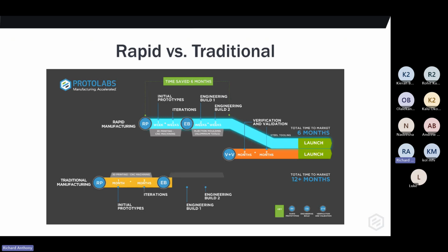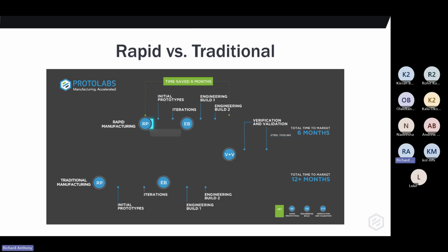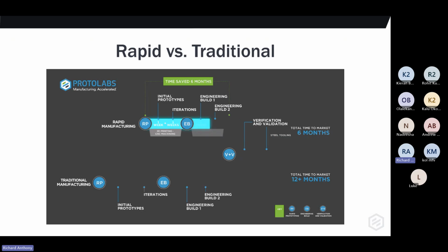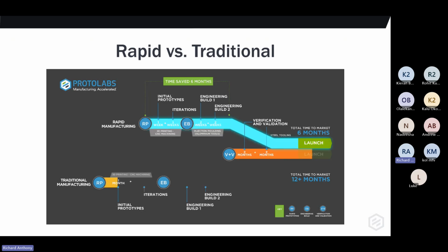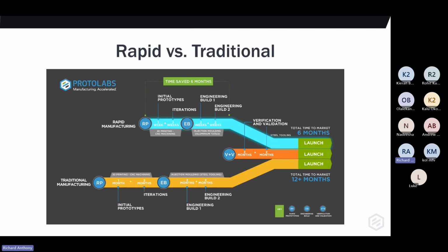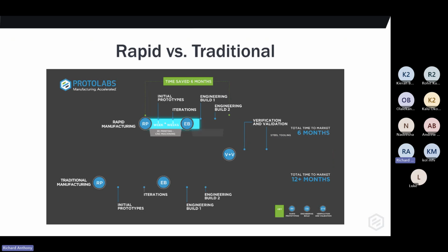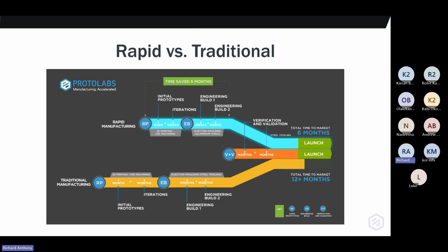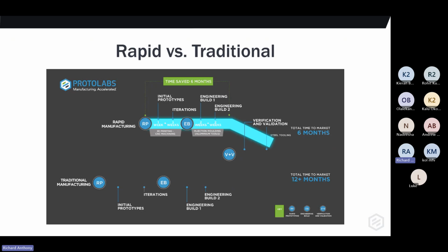So for our injection molding process, we have 2 mold life options. When you place an order for a mold tool, we have what we call our prototyping mold life, and we also have an on-demand manufacturing mold life, limited and unlimited. With the limited mold life, we guarantee the mold for 2,000 parts off that mold. You'll see a lower mold cost and a slightly higher piece part price. So the idea there is you make the saving on the mold tool because you're never going to have that many parts off it to make a saving in the long run on the parts.